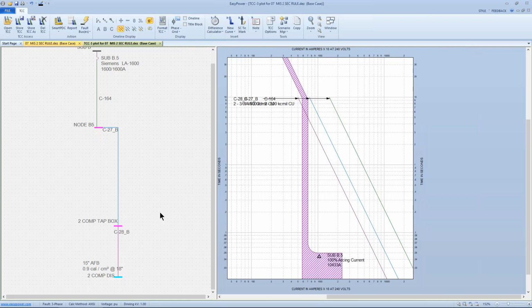So the point is, just automatically applying the 2-second rule is, in my opinion, not the first place to go. You really do want to understand what's going on in your system, because places where you have excessively high current, the system should be designed to take care of itself. And so it's a misguided approach to just take the 2-second rule as a first place to start.